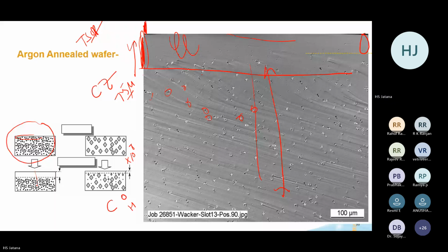And the first step in the process, for technologies below 100 nanometer, is basically the definition. You have to define the areas, active area and field areas. What does field area mean? Isolation. You have to define the isolation, and the active area is where the transistors are made, and where the transistors are not made will be the field area, which is the isolation area.